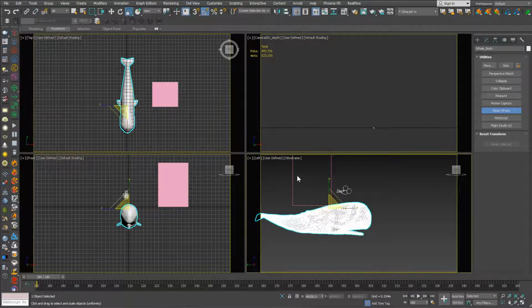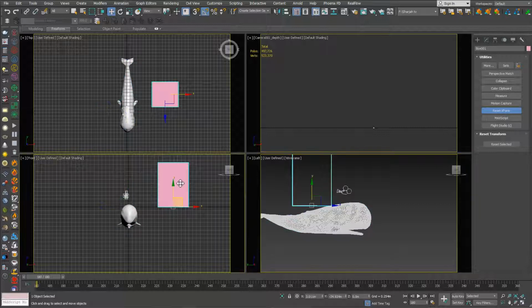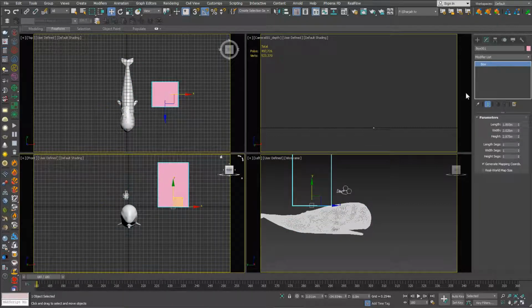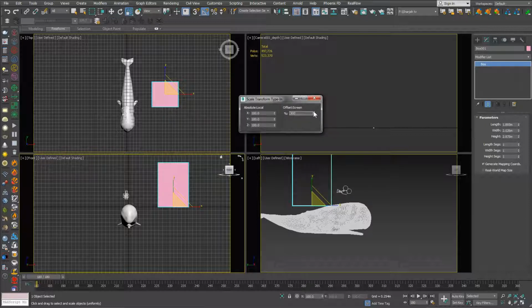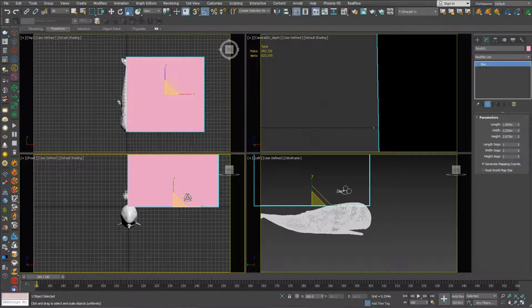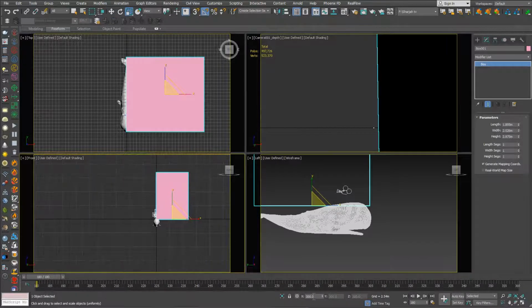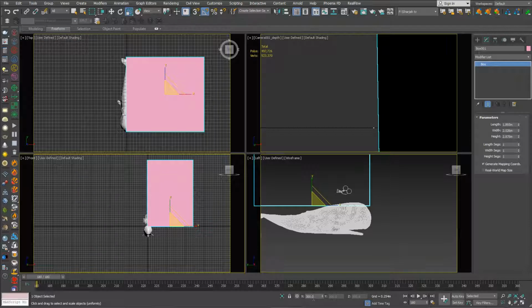Another way to do this is always to rescale your geometry at the sub-object level. As an example, if this has a scaling of 300, now I have 300 units, and here it's 300. If I need to change the scale here in my scene but keep this, all I need to do is apply XForm.